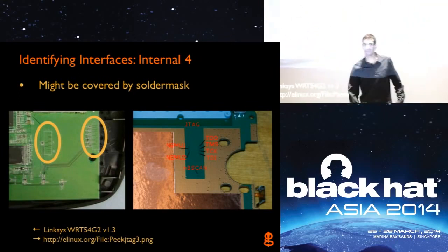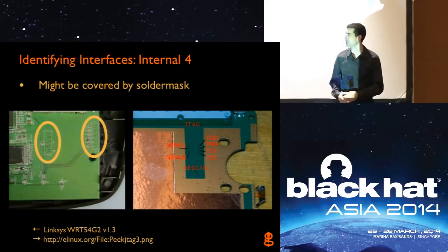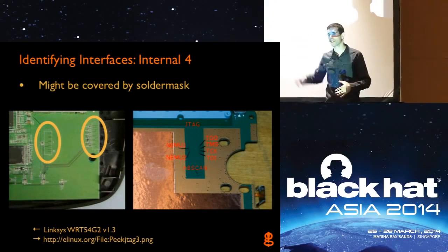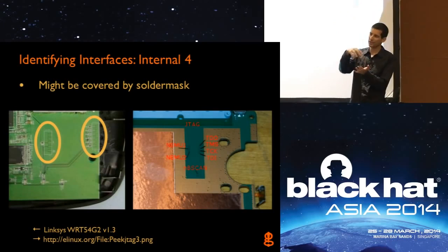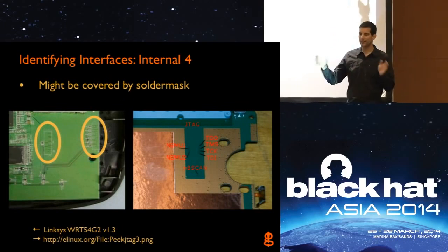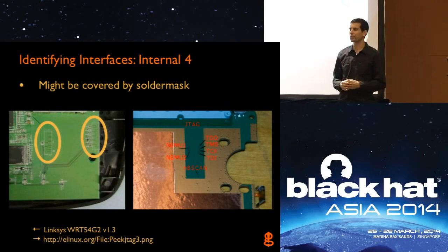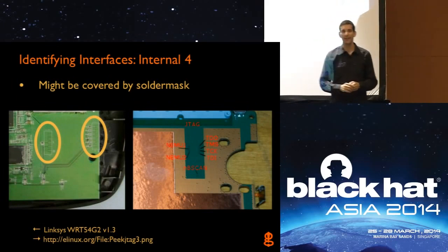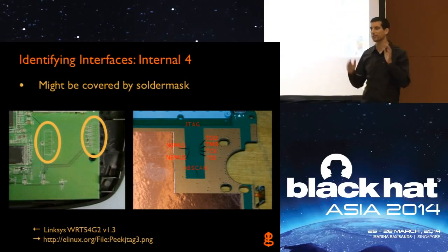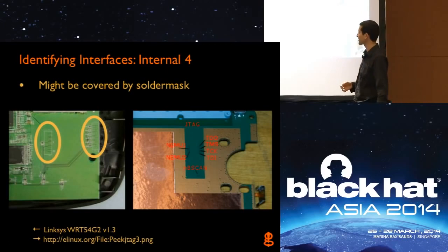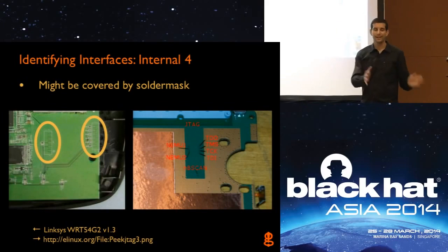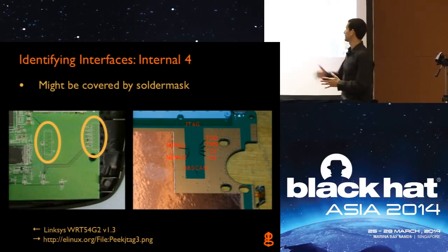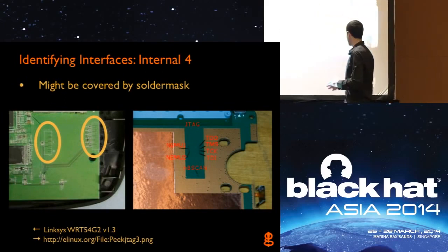solder mask. So it seems like maybe during manufacturing, or maybe during development, that area was exposed, so developers could have some connector plugged in or something like that, and then they just changed the solder mask plot when they were manufacturing their boards to just cover that over. That's a very low cost, easy thing to do. Changing the mask is not a big problem during manufacturing and during PCB fabrication. So maybe they did that to cover it up, knowing that end users aren't supposed to touch those things. Same thing on this side.